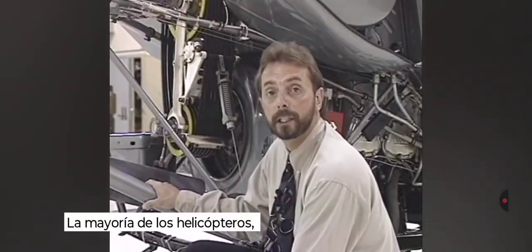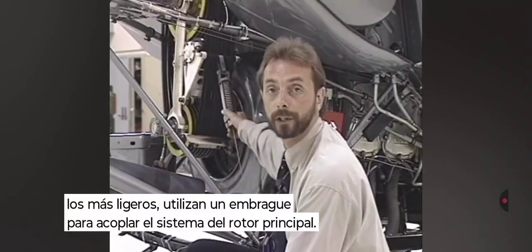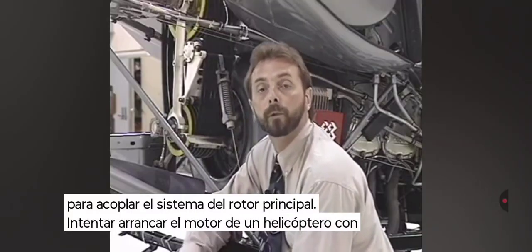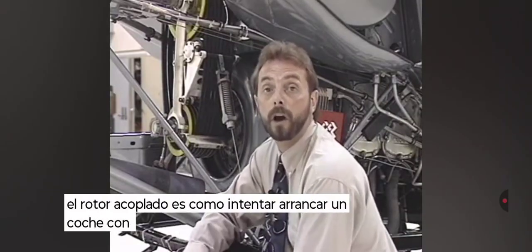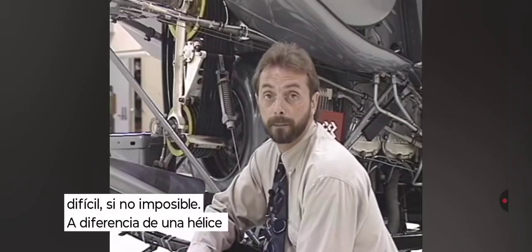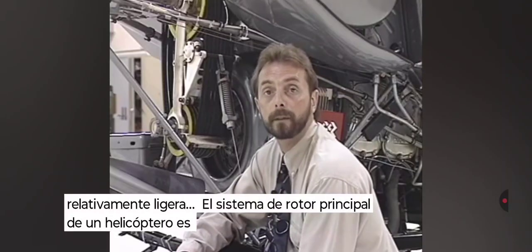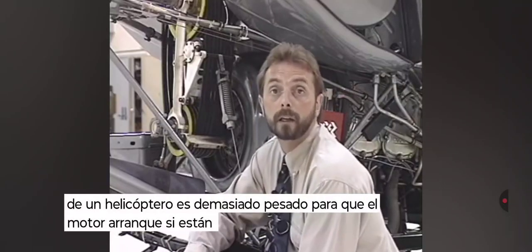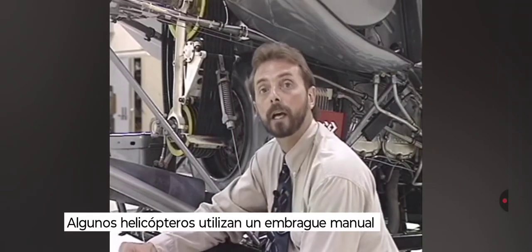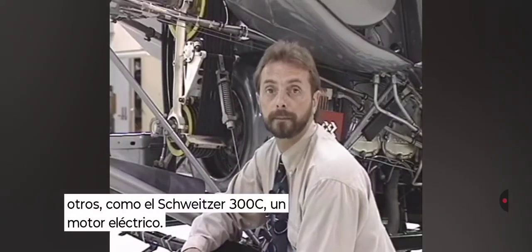Most helicopters, except the very lightest ones, use a clutch to engage the main rotor system. Trying to start a helicopter engine with the rotor engaged is like trying to start your car while it's in gear. Pretty difficult, if not impossible. Unlike an airplane propeller, which is relatively light, the main rotor system of a helicopter is too heavy for the engine to start if they're directly connected. Some helicopters use a manual clutch, and others, like the Schweitzer 300C, use an electric motor.